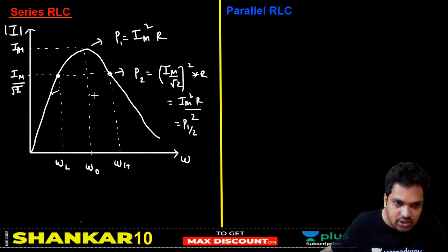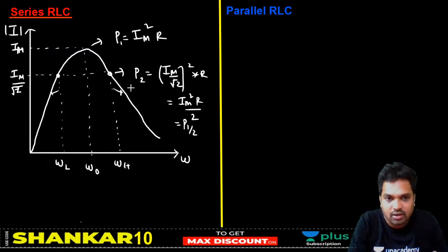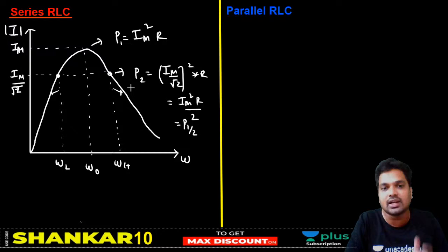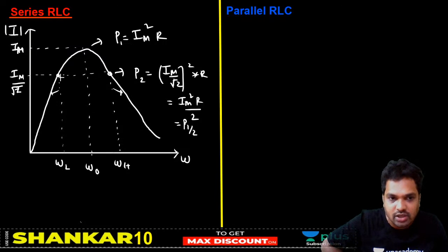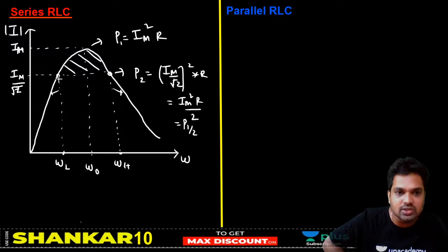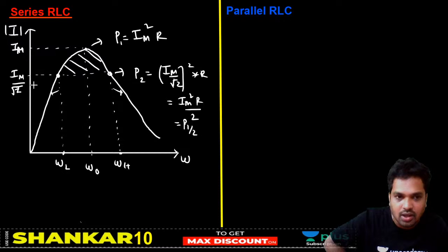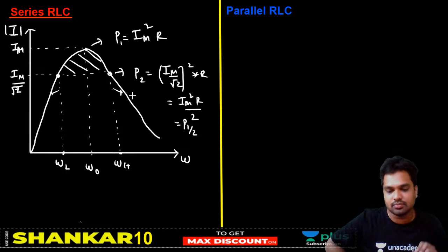If you go below this frequency or above this frequency, the response will further fall. That is why these points are called half power frequencies, or what we call lower and higher cutoff frequencies. We generally take this part as your response pass band and this part as your stop band. That is, from this point to this point, I guarantee minimum 50% of my response. In this frequency range, my response will be minimum 50% of the maximum possibility. Below this, the response will fall.